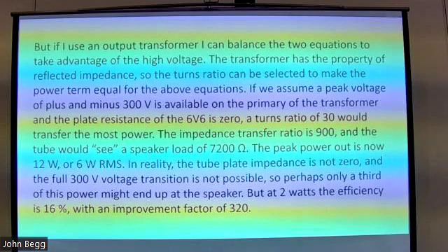Right. So the coil could be like 6 ohms or 5 ohms DCR, and when people say 8 ohms, it's only nominal. That could be at like 1,000 hertz. It's an approximation. The whole thing is an approximation because I say at the end that you may only get a third of the power anyway.